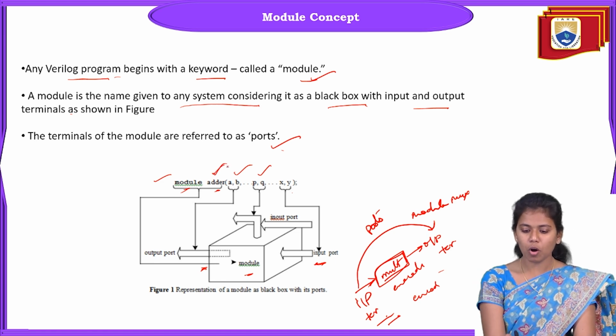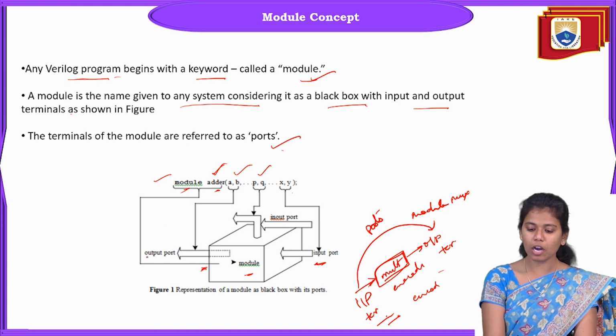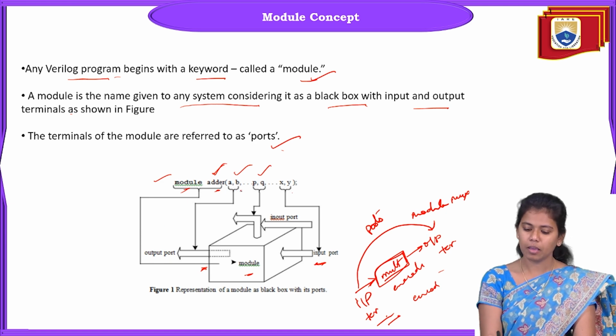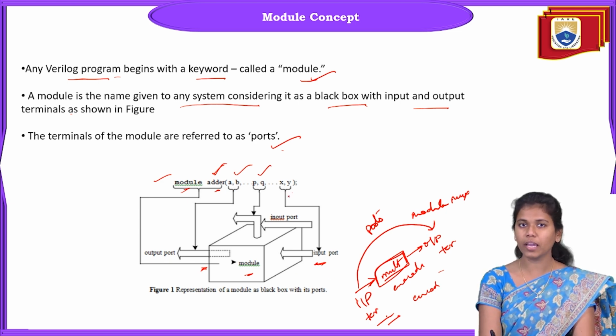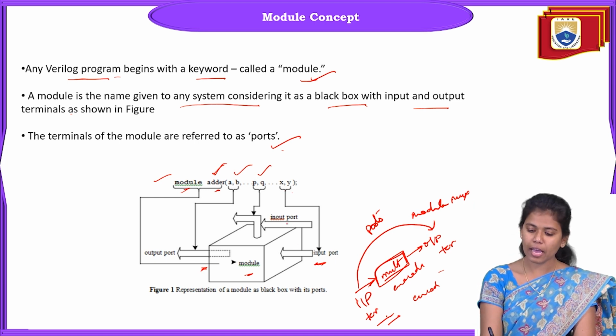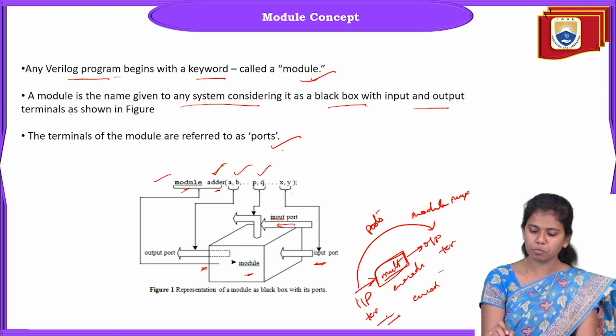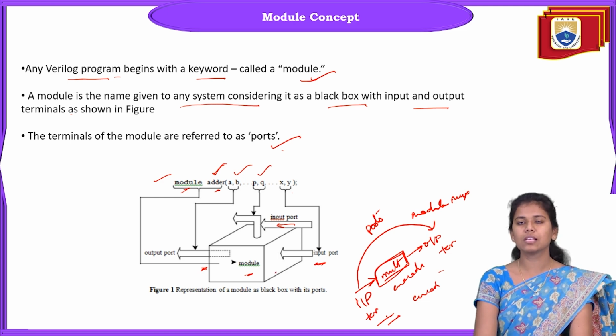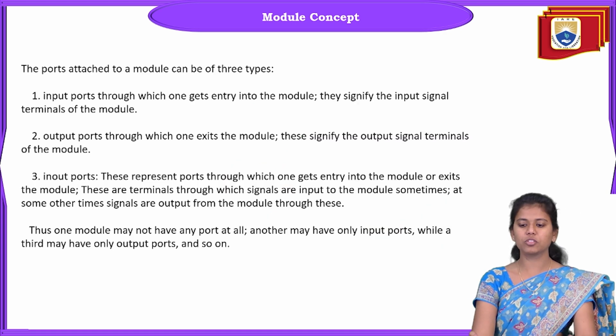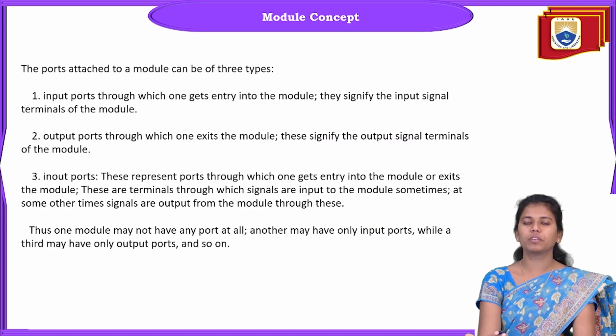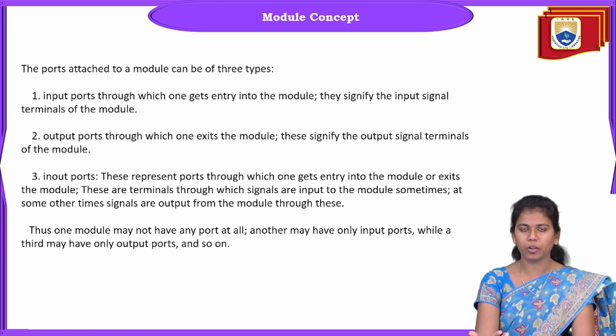So module adder, my output ports are A, B, my input ports are X, Y, and I also have in-out ports, P, Q. So this is how you will represent the module. Coming to the in-depth, we discuss what a module actually is.